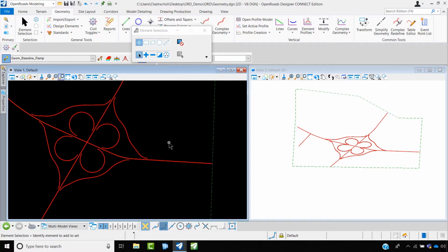Or say you might be working with your AASHTO standards and you want to see whether the values being assigned in concept station are following the standards. Then these design standards assist the designer to monitor the required curvature and other checks when performing the geometric design. So where do you find these standards?